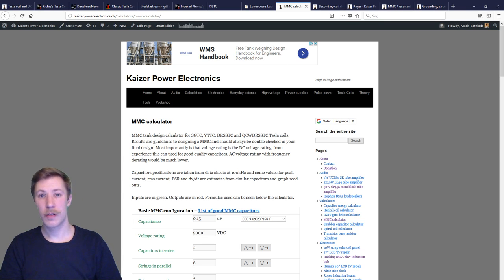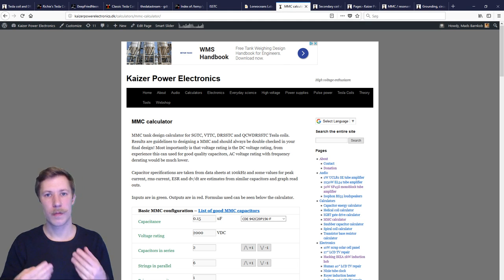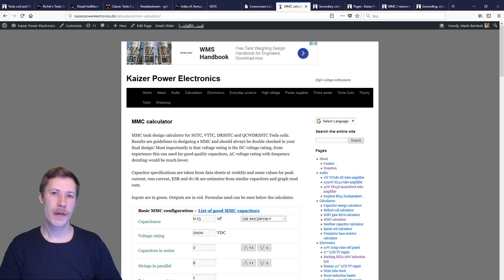So that could easily become a problem if it's not really controlled, that your current paths and the inductance of such an MMC. Because the good thing with the actual capacitors or snubber capacitors is that you dissipate up to 2/3 of the heat inside of it through the terminals. And often you can mount these on some larger copper rails or something like that. But I think the small size of the SMD capacitors itself is a bad starting point from a thermal management perspective.